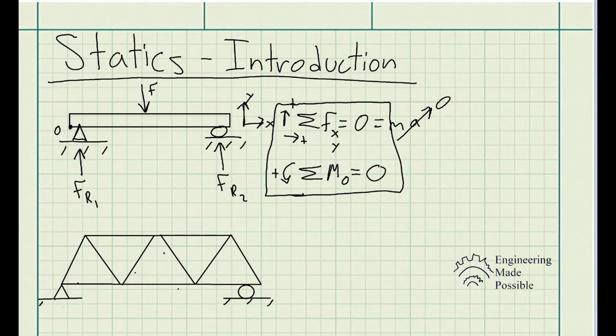In this kind of structure, we know the external forces acting upon it, which could also be distributed loads, meaning force per so many feet, exerted as a uniform distributed load as it's otherwise called. If we know the external forces and we're able to solve for the reaction forces here and here, we're essentially able to determine, at every single point where these beams interconnect, all the forces along every single beam.